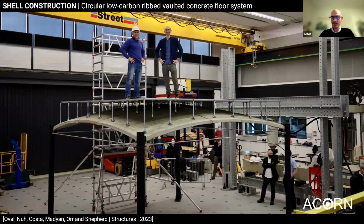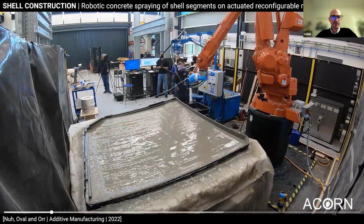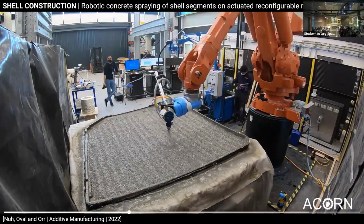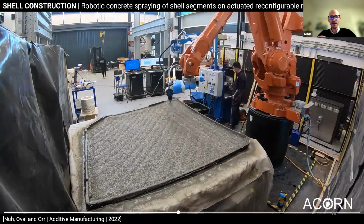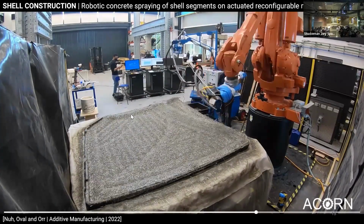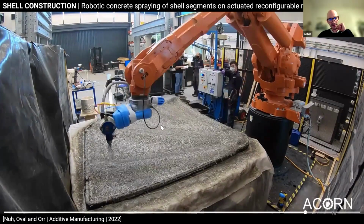And I want to show you how, in that case, to build this circular structure, topology was a key aspect as well. So to produce them, we actually use robotic shotcrete or concrete spraying with glass fiber reinforcement. That's why it has this look. Yeah, what was key was the path planning. So you can see we're spraying in different directions. You can see it from the kind of strips. To optimize the structure, it doesn't have the same thickness everywhere. So that's why you have these kind of ripples.